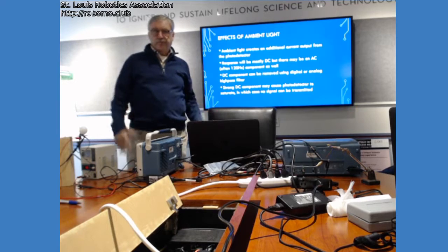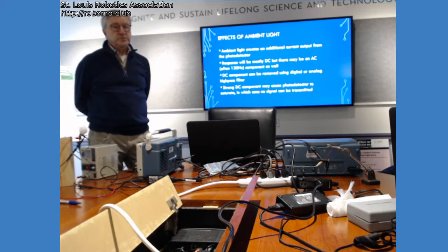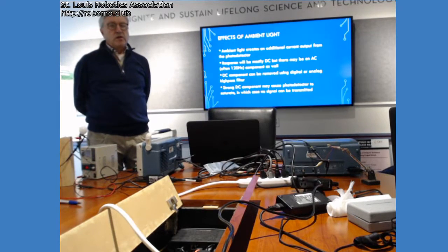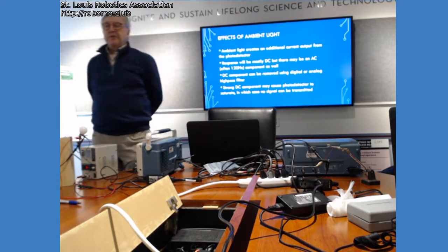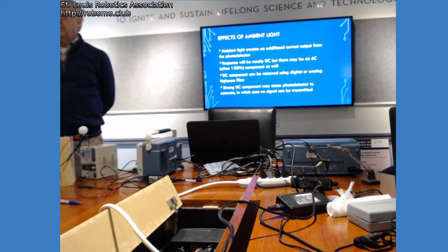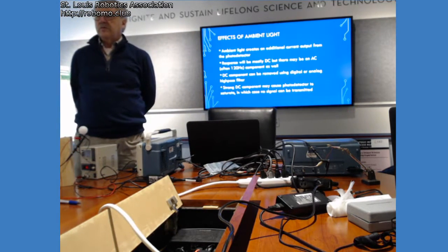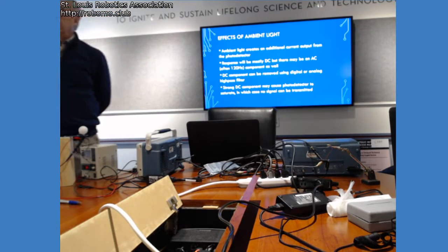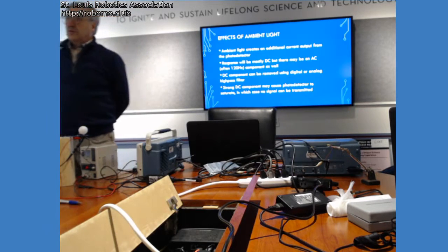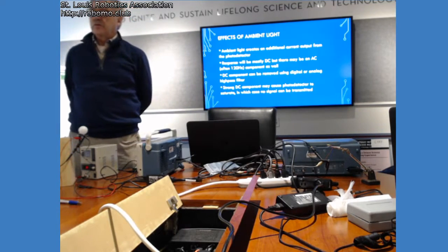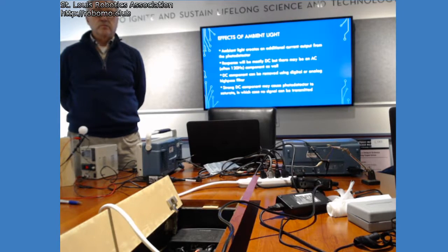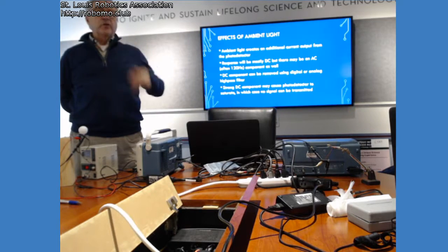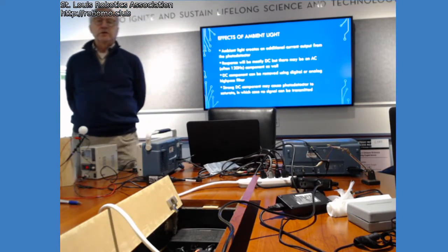And so I ripped some apart. The one thing I couldn't tell was whether they did anything to smooth the voltage. Like a good power supply, you should have very little ripple at all. Probably not. All it takes is a capacitor across that output to give you enough delay time to do that. Well, literally, you should be able to see that capacitor, and it can't be a tiny capacitor. It's probably a tantalum, something big enough to see. Did they have a capacitor in there at all? Yeah, they had everything a power supply would have, but no big capacitors.